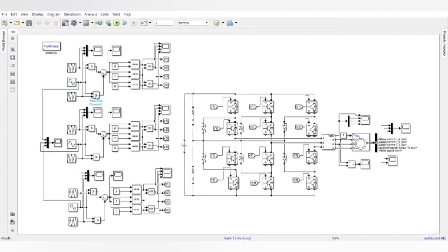These are the relational operator blocks, and 2, 1, 0 are the constants used as the relational operator inputs, and OR gates or logical operators are used in the control circuit to perform the logical operation. R1, R2, R3, R4 are the go-to blocks that are used for passing signals from one circuit to another. Now let us discuss the main circuit components or blocks.